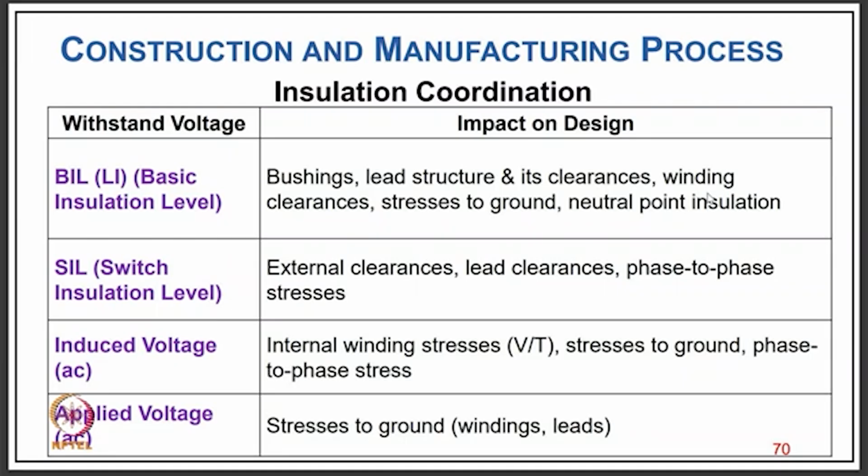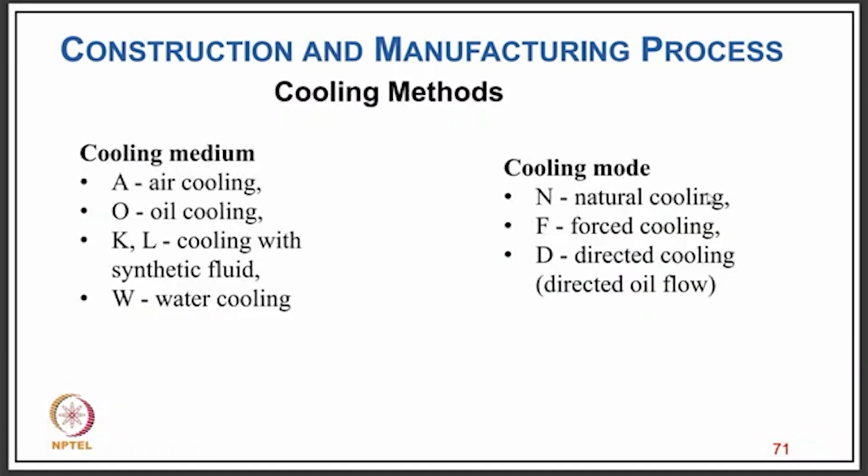Then we have in SIL, the switching insulation level, the external clearances, lead clearances, and phase to phase stresses. Then we have induced voltage, with internal winding stresses, stress to ground, and phase to phase stress, and applied voltage, that is stress to ground for winding and leads.